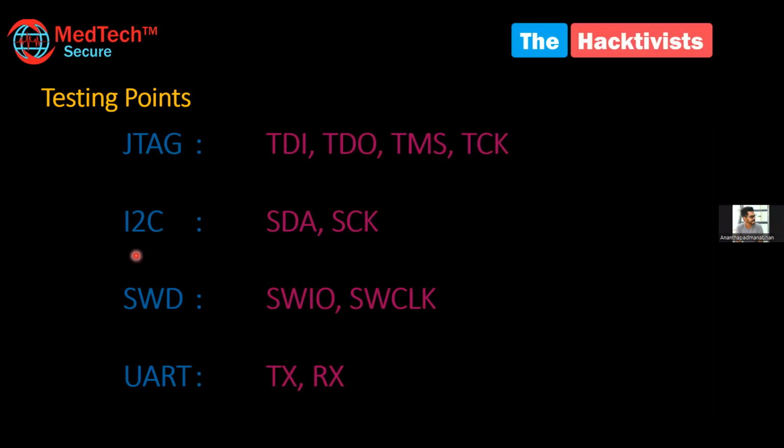And if it is using I2C, we have to find out SDA and SCL. For the SWD protocol, SWDIO and SWCLK need to be found out. And for the UART, as we looked at initially, we have to find out the transmitter and the receiver points. These are the testing points for these protocols.